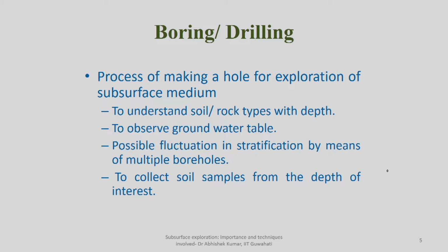When we go for boreholes, depending upon what kind of structure is there and what its importance is, there are guidelines which tell you the spacing of adjacent boreholes and the depth of the borehole. And the last and foremost important thing is, this way you will be able to collect soil samples, even rock samples, from the different depths of interest.